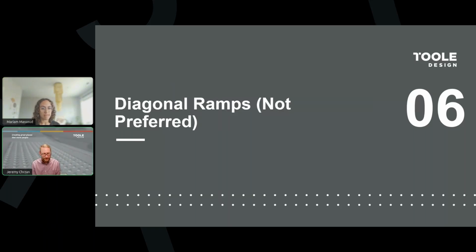And that's the real challenge with that style of detectable warning surface, that they might be great on day one, but a year or two later, the domes will have chipped off of them, a couple of the bricks will have settled, and I've seen plenty of examples where some of them are missing. And so it just means more cost for the agency to maintain.